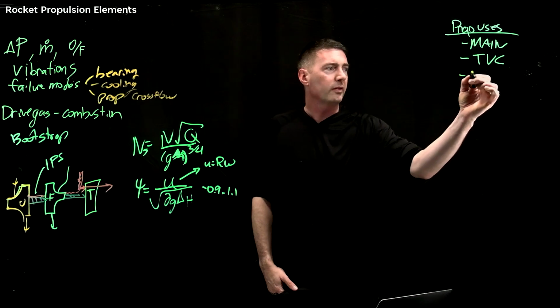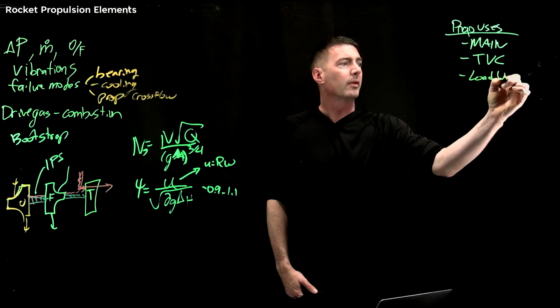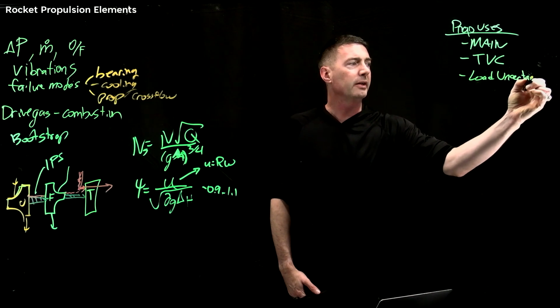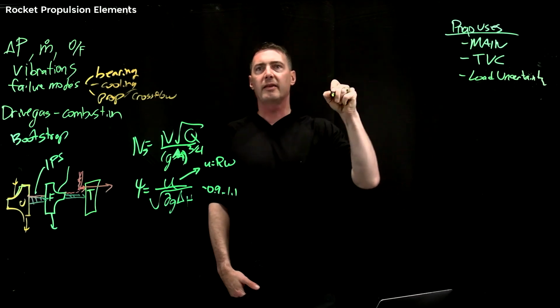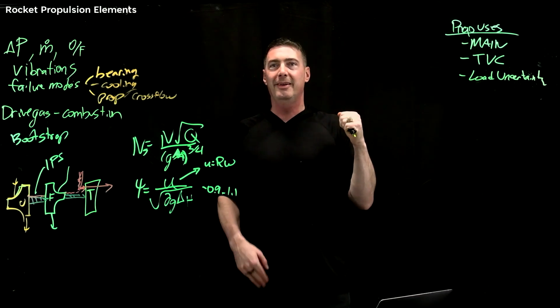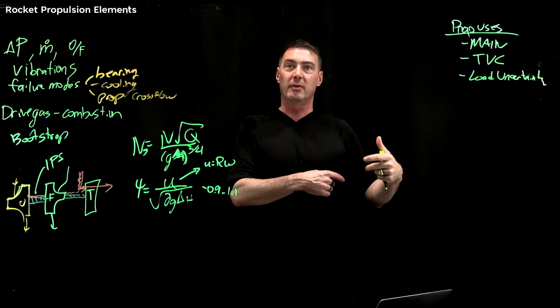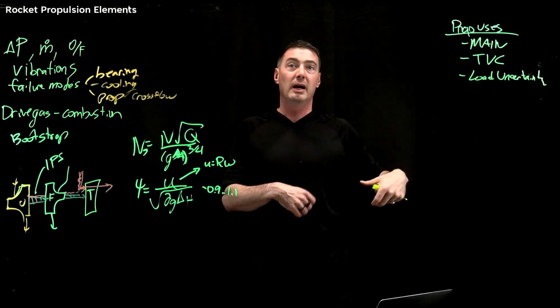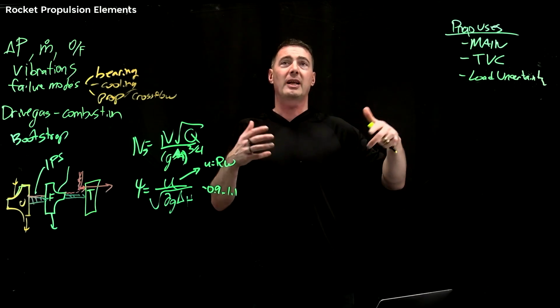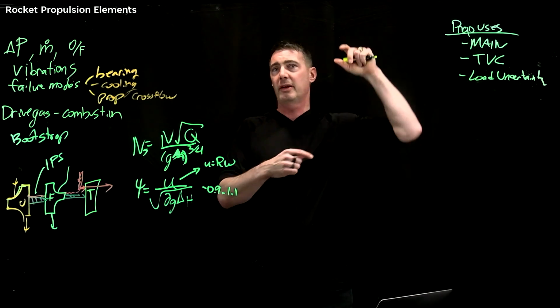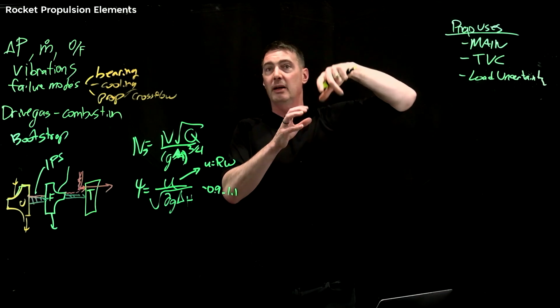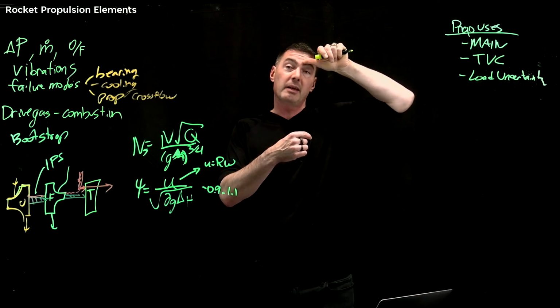There's a load uncertainty. So you might think, no, I'll just load exactly this many kilograms. But in order to do that, when you're loading, you have to have really good mass flow rates. And if it's cryogenic, if you're trying to understand how much cryogen you have in there, you also then have to collect all of the gaseous stuff that's boiling off at some point. So that can be really challenging.